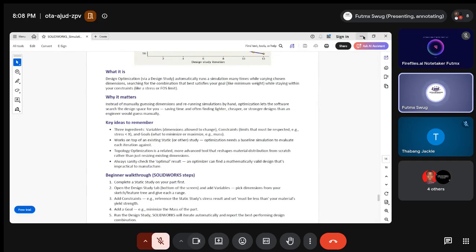For example, for a CubeSat, they have form factors and particular loading conditions that the CubeSat is supposed to withstand. So my ability to design and make sure that my design is optimized for that loading condition matters, and I also have a particular safety net, so that even if I apply more than that loading condition, like I said, designers or engineers, we over design for extreme cases, my parts will still be able to survive.